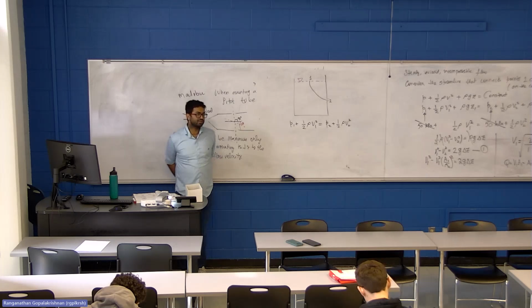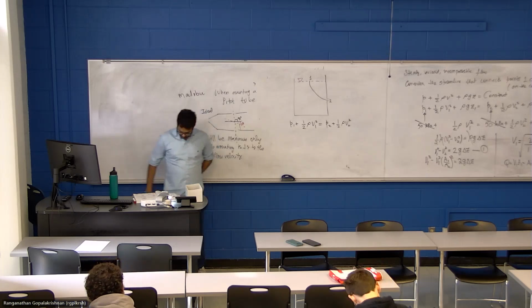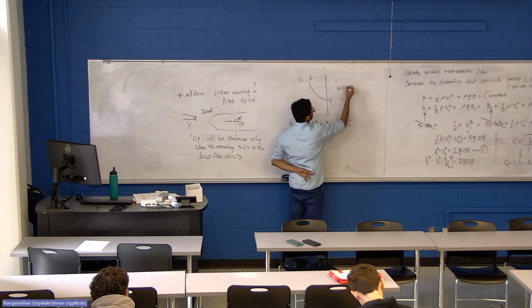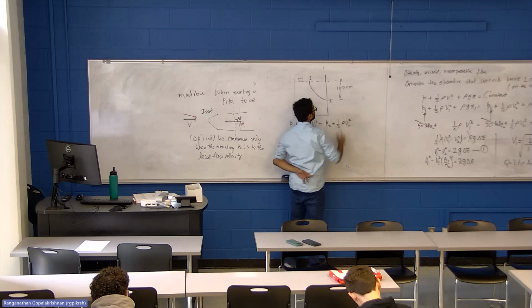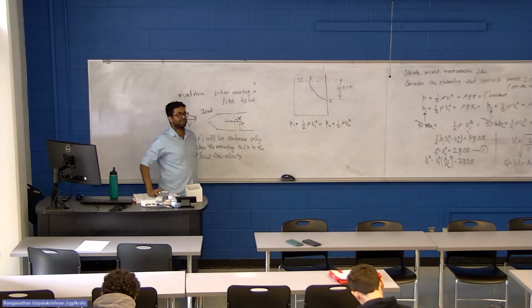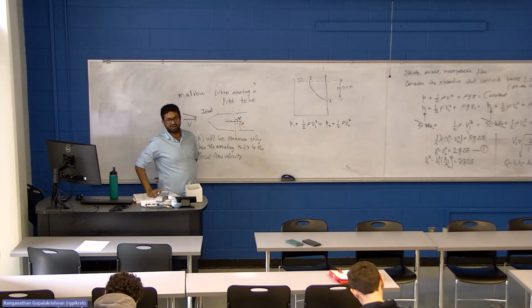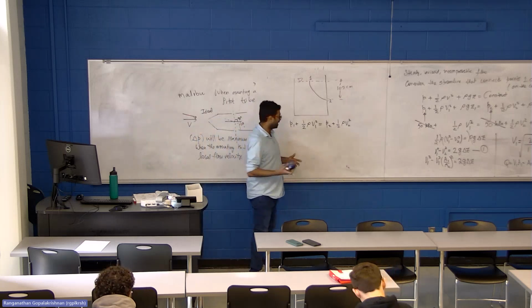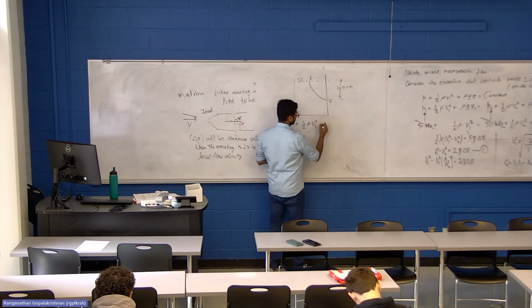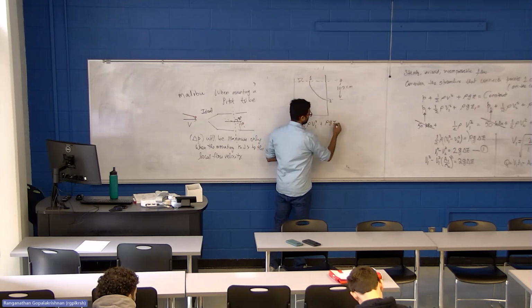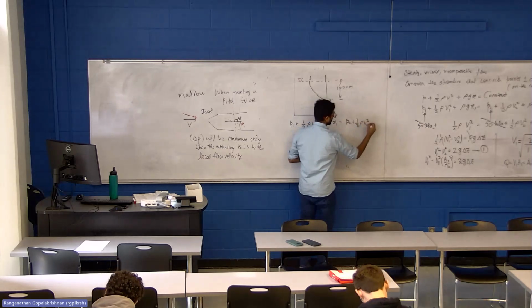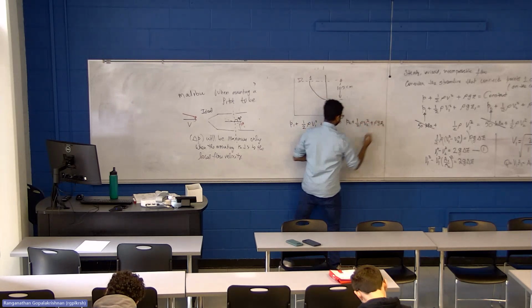Everybody is okay? I just didn't even write about gravity, which is the height difference here, about 10.5 centimeters. I made an engineering judgment that over 10.5 centimeters, the height difference is not important. See, that's bad practice. I can do that because I'm not the one taking the exam, but you are the ones taking the exam. So we'll write P1 plus half rho V1 squared plus rho g Z1 equals P2 plus half rho V2 squared plus rho g Z2.